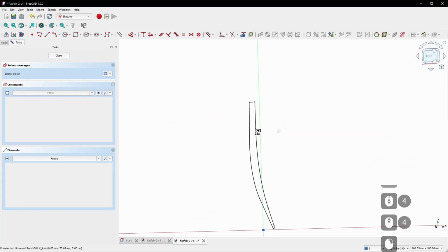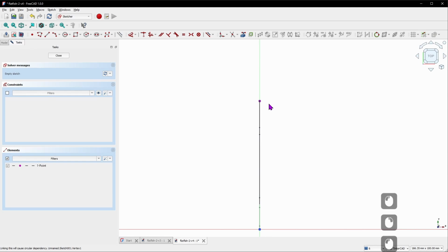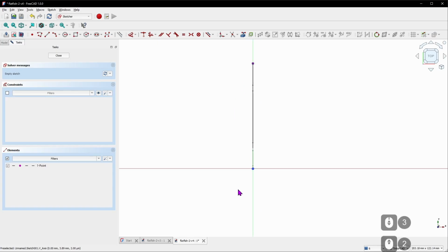And the first thing we're going to do here is come up here and grab reference geometry and grab a point from the back end of that sketch so that we have our right dimensions. Now I'm going to use a B-spline to describe the shape of this. But in order for you to follow along and get the same shape as I did, I'm going to fully constrain this B-spline, which I don't always do.